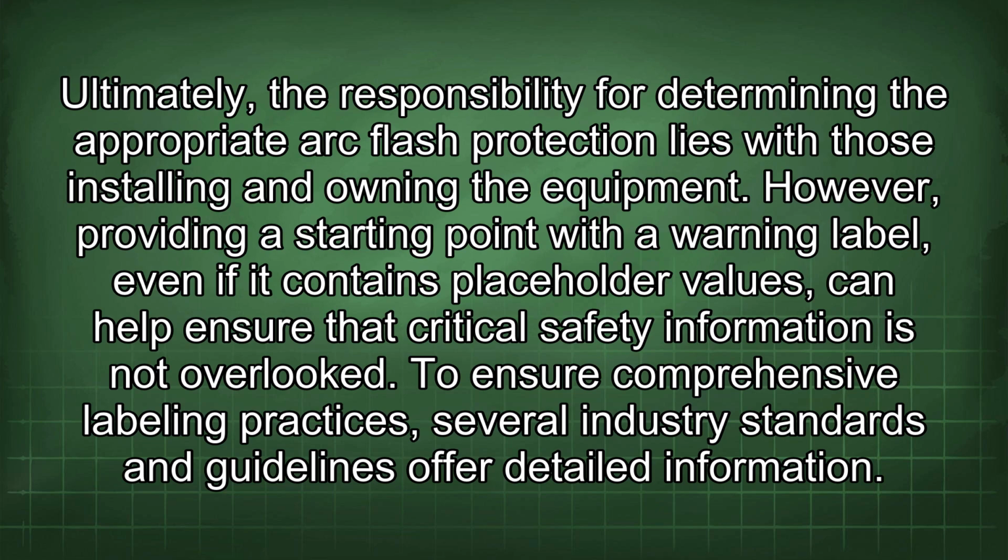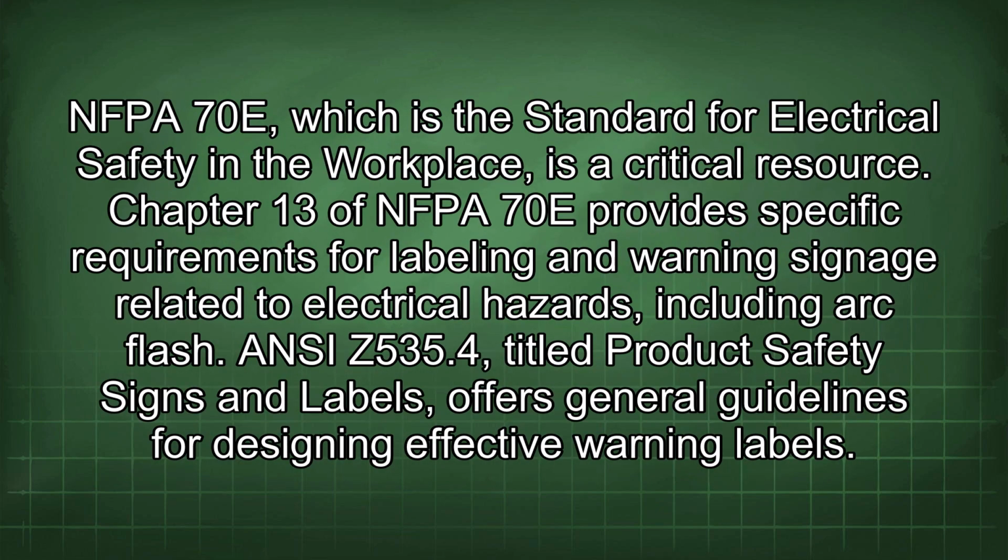To ensure comprehensive labeling practices, several industry standards and guidelines offer detailed information. NFPA 70E, which is the standard for electrical safety in the workplace, is a critical resource. Chapter 13 of NFPA 70E provides specific requirements for labeling and warning signage related to electrical hazards, including arc flash. ANSI Z535.4, titled Product Safety Signs and Labels, offers general guidelines for designing effective warning labels.